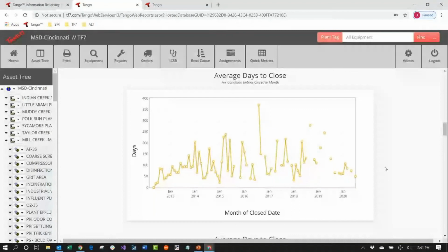It allowed them to make adjustments so that they were reassigning some of the personnel by saying maybe we don't need to be doing that monitoring every 30 days, that vibration route. We can do it every 60 days or maybe even 90. And we can take those extra man hours, and they assigned some of those techs to become more active in starting some root cause investigations and looking to mitigate the reasons that they might have been predicting problems over and over.